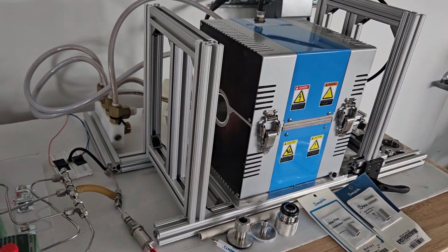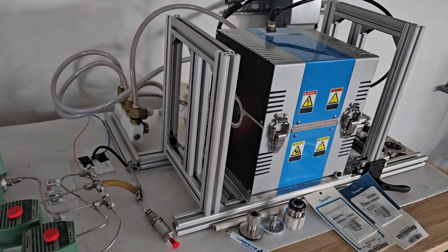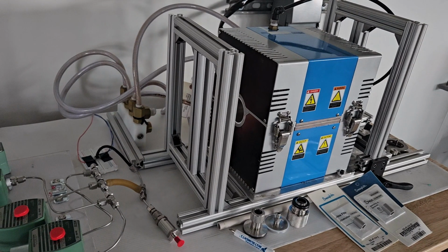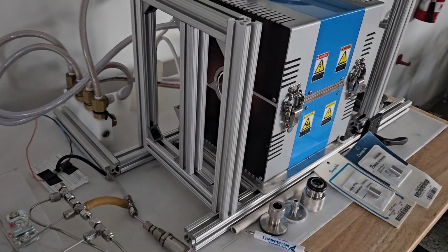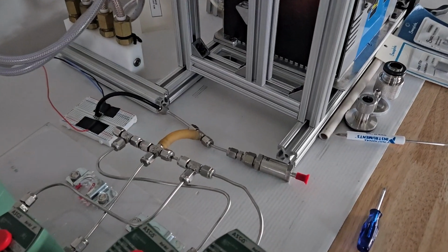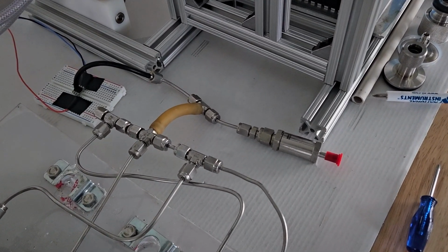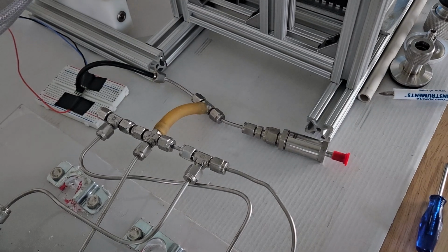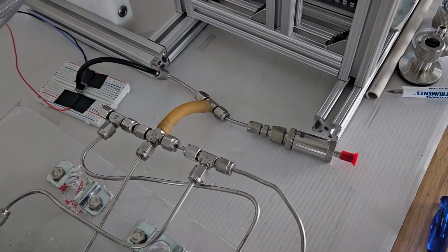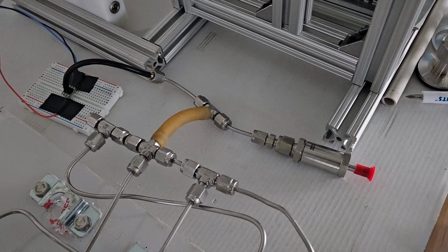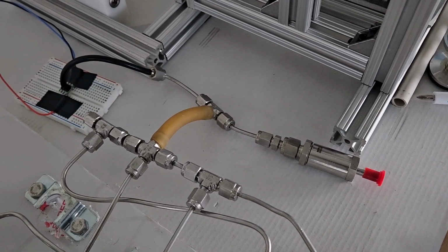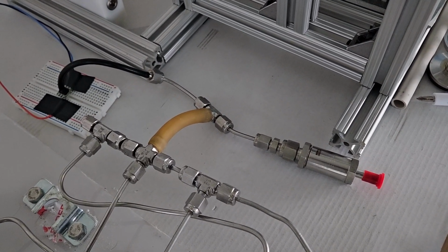It is here that the combined gas would mix with the chemical sponge and release different gases as it heats up to 1800 Celsius and down to 900 Celsius in a continuous cycle that could run for as long as wanted. From there, the gas moves to the T-split. The gas then can move either to the pressure sensor, which reads the pressure in the system compared with the atmosphere, or through the filter. This filter slows down the gas and builds up the pressure in the system, allowing for the pressure difference to be significant enough to be properly read.